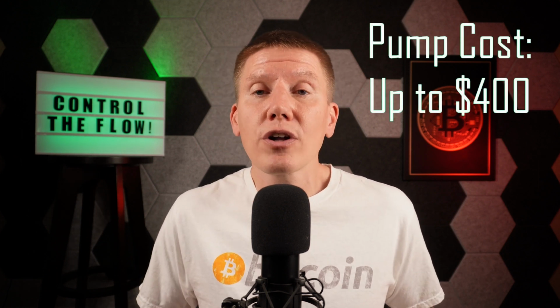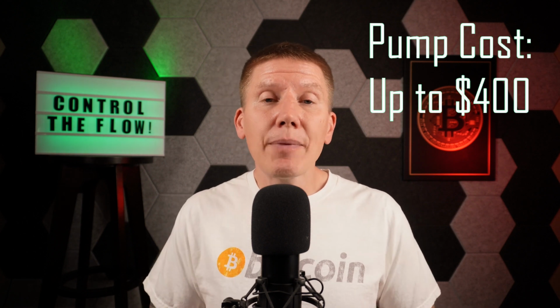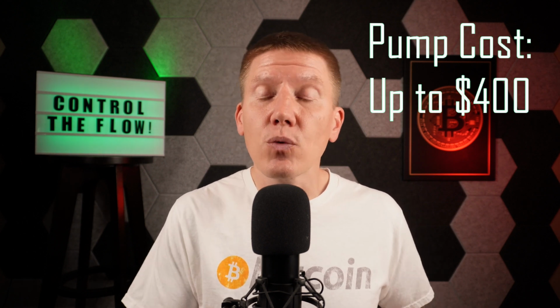Now, in looking at these pumps, you'll find that they're not that cheap. They can run up to $400 or more per pump. However, they will run for a long time if treated well, and the key to a long life is to avoid any solids or particulates from entering the pump and causing damage within the internal impeller assembly. And the best option to avoid damage is to put a filter in the system before the pump.